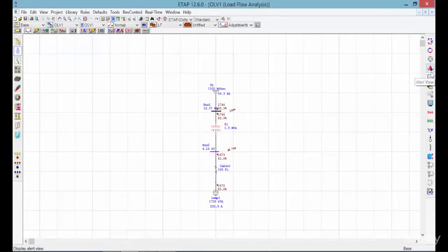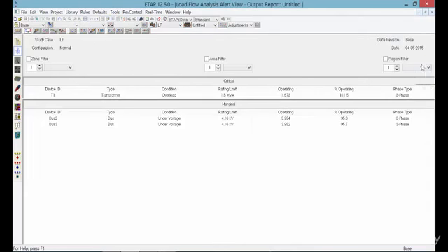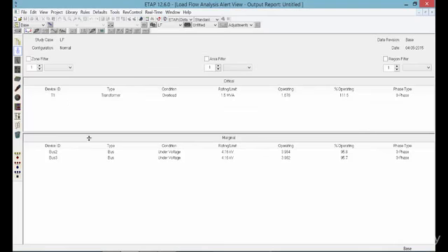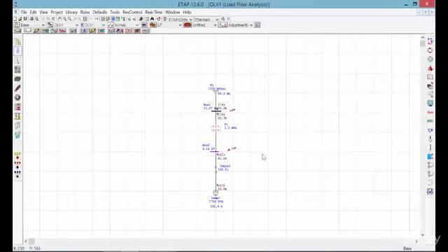And if we again see, the yellow color of the alert mode turned red, which means that we have something critical happening, which is the transformer went to the critical table, if we are exceeding 100% of the capacity of the transformer. So now this way we can keep track of what equipment, what buses are critical and marginal. And again, see that bus 2 stays in the marginal region, but the transformer is critical.